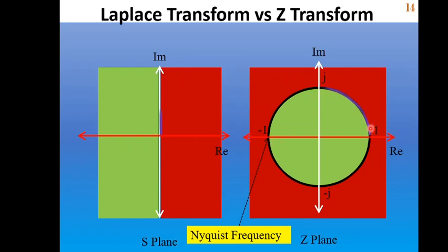This point shown in purple color corresponds to the line where the impulse responses neither grows nor decays over time. But the frequencies along this line keep increasing from DC point. Points shown in yellow color are identical to the points shown in purple color, but they indicate negative frequencies.